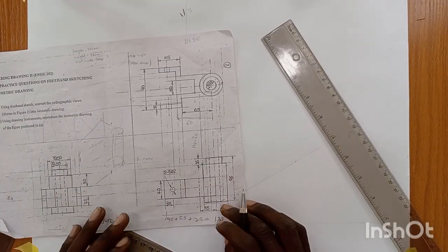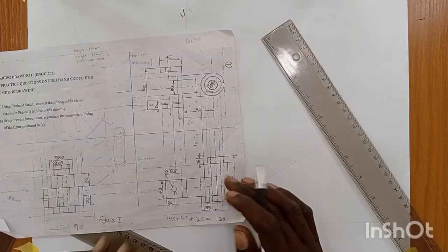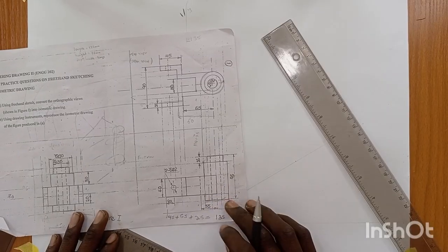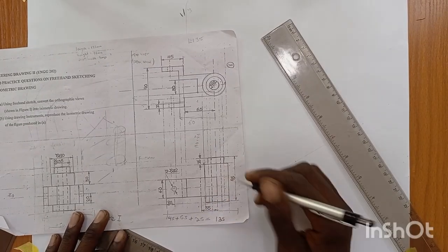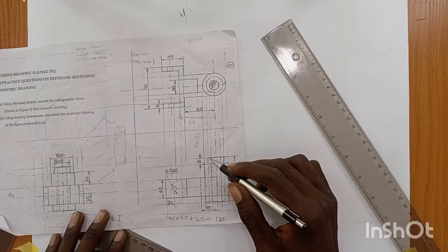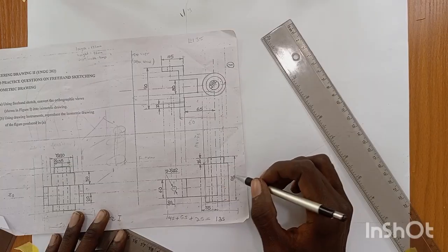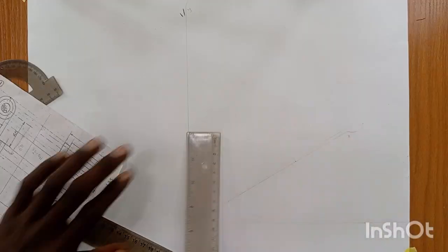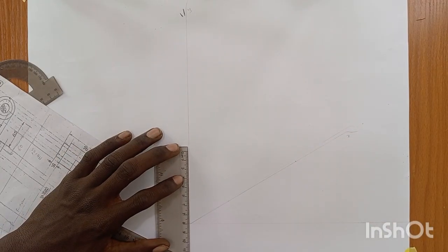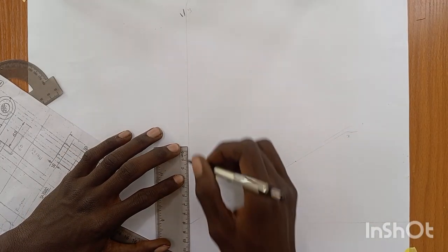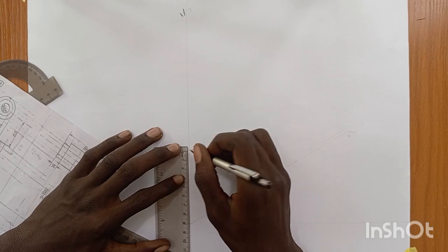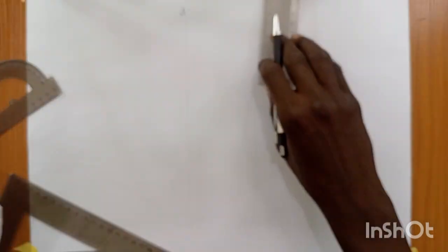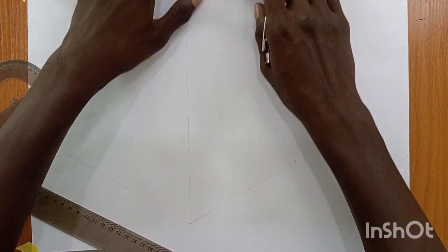But because we have a cylinder standing up, we have two cylinders, we are going to first draw the bigger cylinder. So now, to get the height of the bigger cylinder, the height of the smaller cylinder at the top is given as 16. So we take 96 minus 16, which is 80. So now we're going to measure 80 to have the height of the bigger cylinder. When we are done drawing the height of the bigger cylinder, we'll now move forward to draw the smaller cylinder. We are doing this to make the space very clean and neat for us.